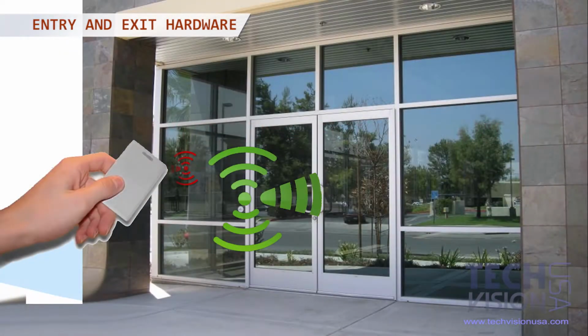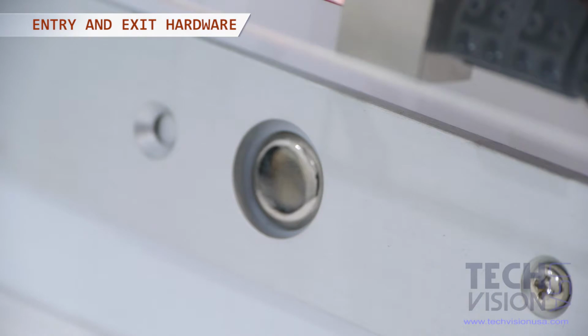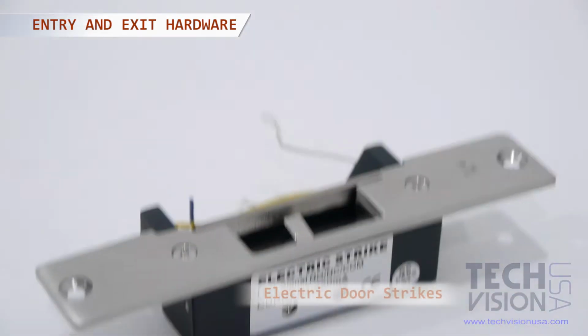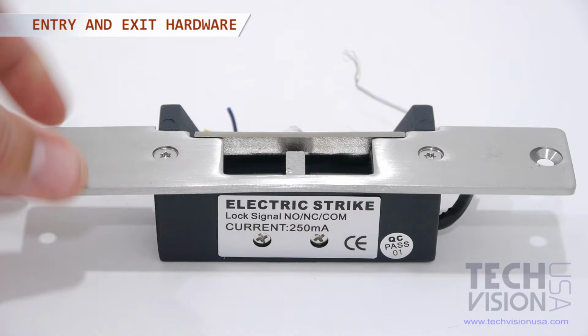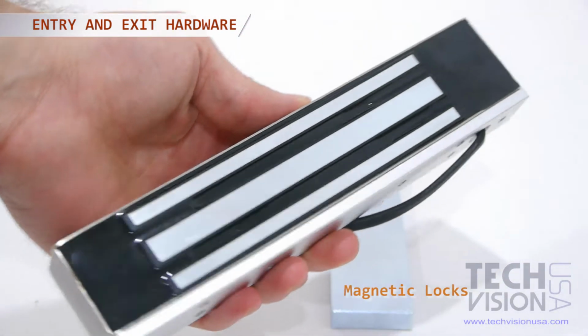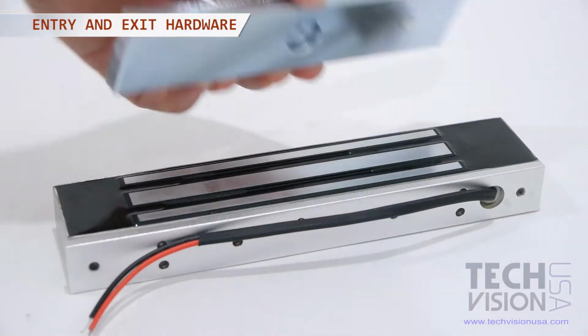Part 4, entry and exit hardware. Once the user has been granted access, it must send a signal to the door to unlock it. In this case, the door must have special equipment that works with the access control system. The 2 most common mechanisms are electric door strikes and maglocks. Electric door strikes will replace your existing door strikes. They are electric powered and will automatically unlock when the user is granted access.